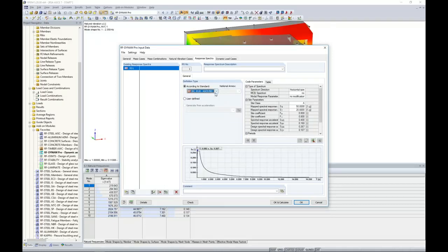So moving forward with the ASCE 7, over on the left, we have some available data that we need to input into the program in order to correctly generate the response spectra for our project today. The first would be the site class, and with the site class, we've determined that with this particular concrete building, we have site class C. We also need to input here the mapped spectral response acceleration for short periods, S_S, as well as for a period of 1 second.